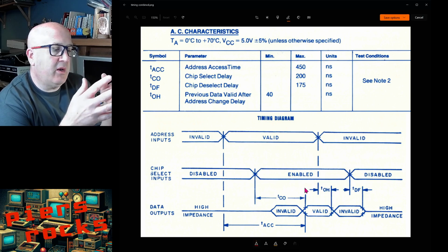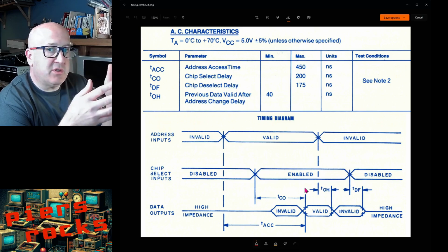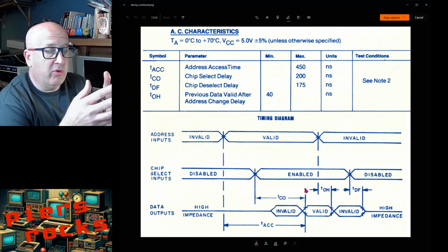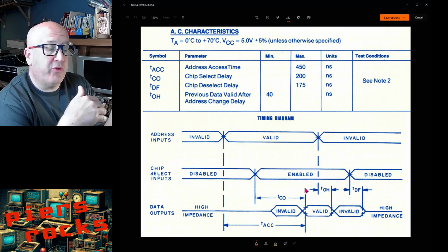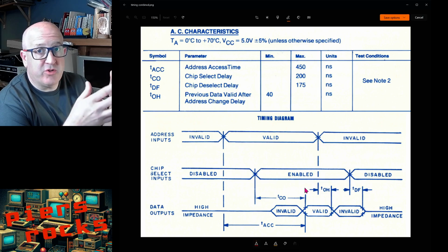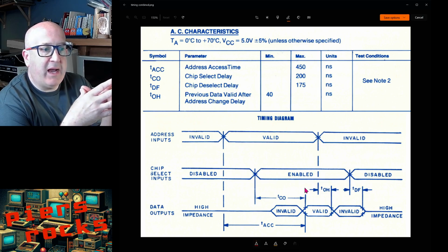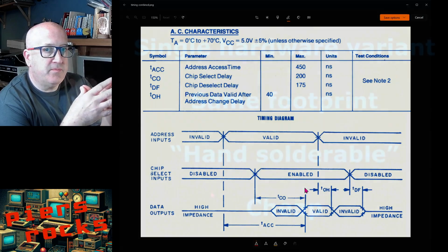And that might sound like quite a lot until you realize things like a single instruction may take 1 cycle, 2 cycles, 3 cycles or more cycles. You may hit flash wait states, which cause your CPU to pause for a number of clock cycles before it can read a particular value, instruction or data from the flash. So actually 20 clock cycles is not very much at all.